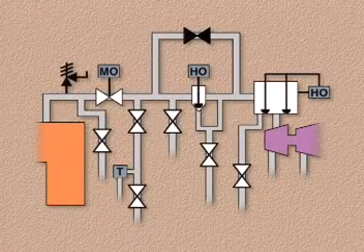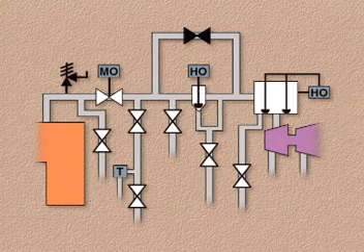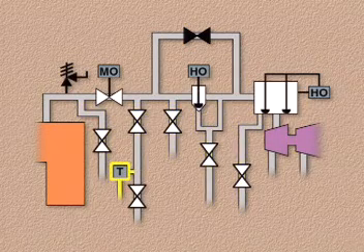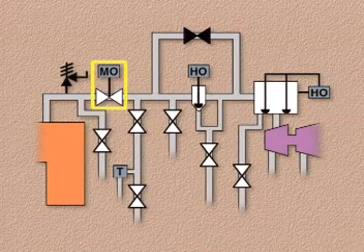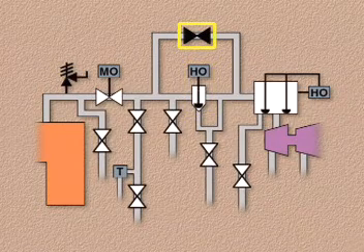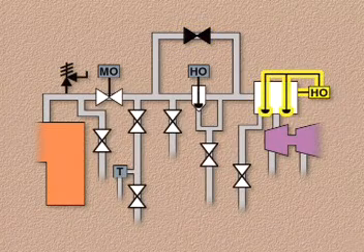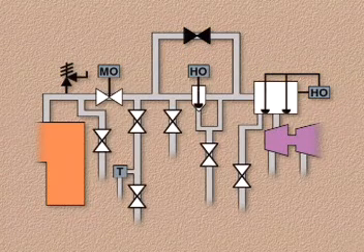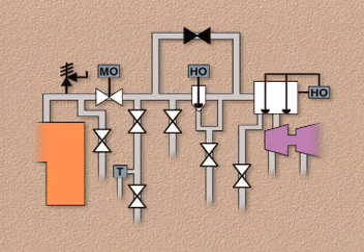To show typical water and steam flows during startup, we'll use this simplified diagram of a main steam system. The system includes drain lines, a steam trap line, a steam trap bypass line, a motor-operated boiler stop valve, a hydraulically operated main steam stop valve, a main steam stop bypass valve, and a steam chest, with hydraulically operated turbine control valves. During plant startup, when a steam system is being returned to service, the valves in the system must be properly positioned for each stage of the startup process.